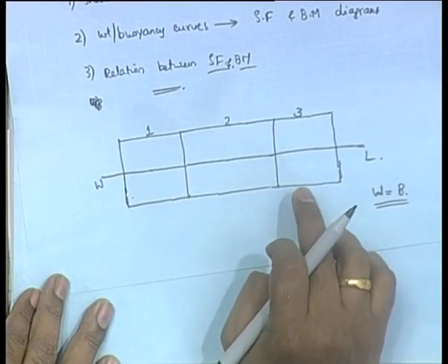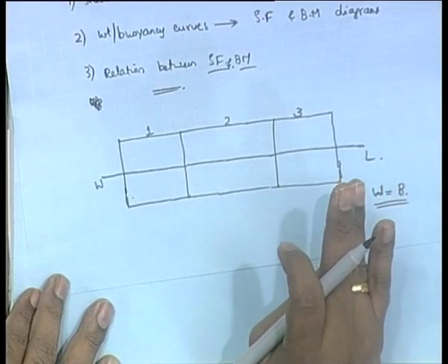Now, you know that in the case of a box shaped vessel, the buoyancy curve will be constant. What I mean is that if the draft is constant in a box shaped vessel, and you draw buoyancy per unit length over this distance, starting from the aft perpendicular to the forward perpendicular, it will just be a straight line, constant throughout the whole length. Buoyancy is not a function of distance.